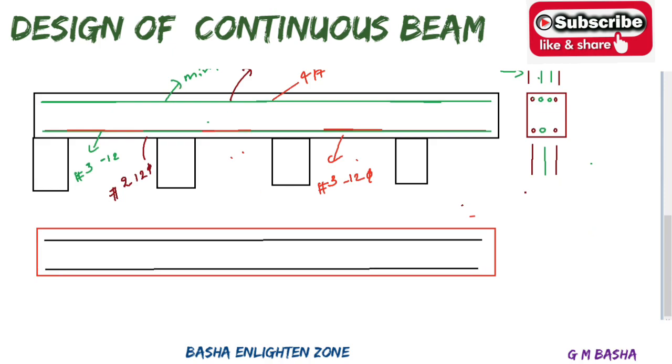So minimum 3 bars will be required in the bottom side, we know that condition. For that, they will keep 1 bar like this, provide the entire bar like this at the supports, and again they will crank here, and again they will provide it to the mid spans up to here. Then again, exactly at the supports, they will provide reinforcement, and again they will crank like this. So only 1 bar they will crank like this.